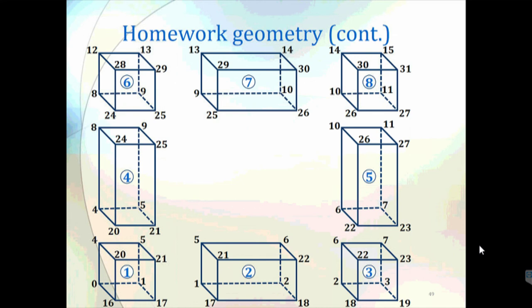You know that this block will share this face with this block. So this face will be defined in the definition of this block, and it will be defined in the definition of this block as well. The vertex points are the same, and the numbering of the vertex points is the same, and so on. Of course, these two will not share because there is a gap in between.